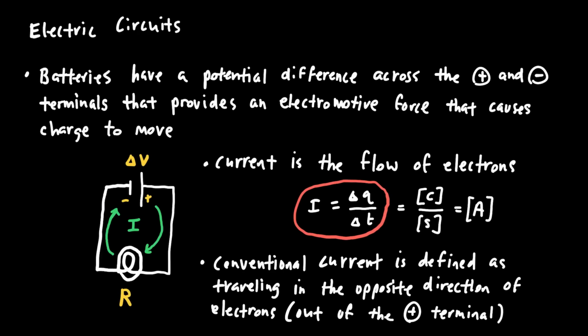And that difference in potential is what provides the electromotive force that drives the electrons through the circuit. And so without an electromotive force, no charges are going to move. And without connecting the two terminals of that battery to allow a route for charge to go from the positive to negative terminals, the charge will not move. So in order to have a circuit, I need to have a closed loop of conducting material, and I need to have a battery that provides an electromotive force.